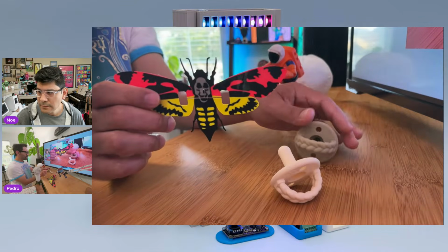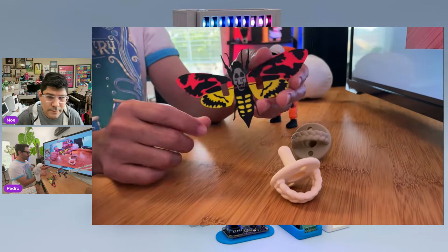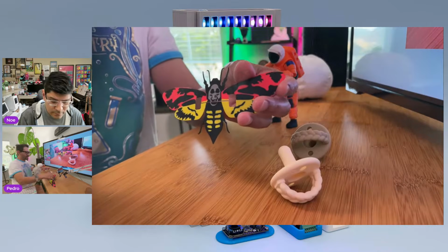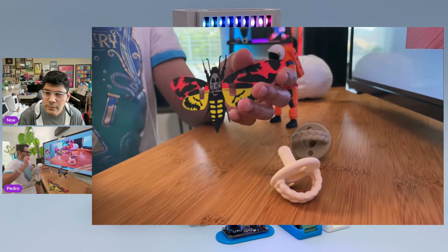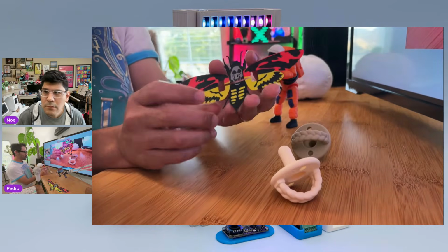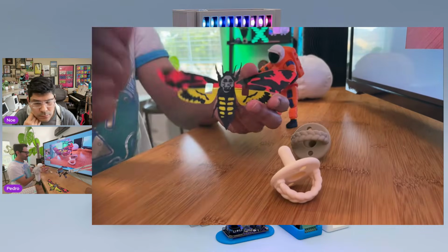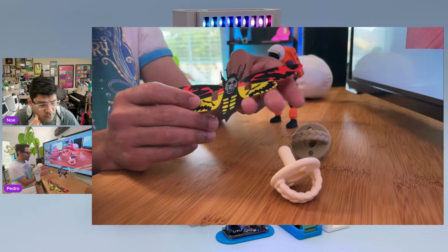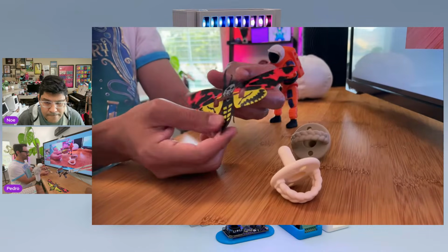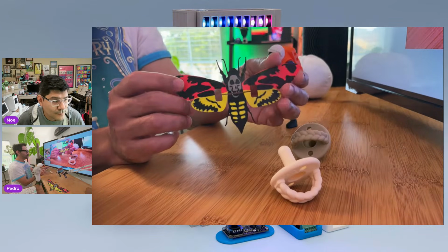And I only had a clog because the Bowden tube that's inside the AMS did wear out. I sent you a photo of that. I should have loaded it up after. I should probably look at how many hours it's been printing for the past 2 years. All of these super long multicolor prints for the time lapses wore out 2 of the Bowden tubes inside that guide the filament into the printer. So luckily they do send the printer with replacements, so luckily I didn't have any downtime for that. Very good.